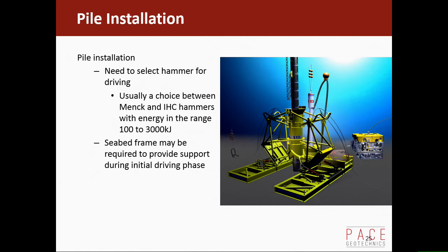Pile installation. I've explained how if you've got a seabed structure, you have guides in the corners to support the pile as it's driven. If you have a mooring pile, or it might be a startup pile for a pipe lay operation, then you can't use a single pile easily. It's got to be supported at the start of driving, and you can use a frame like this.